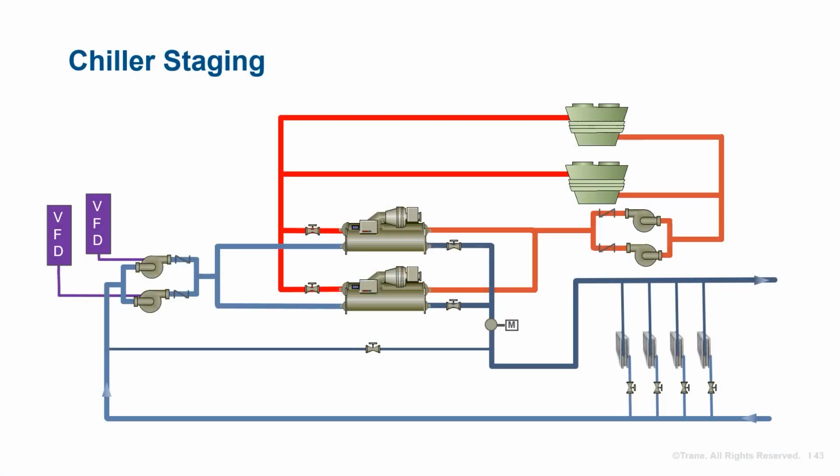The plant configuration we'll look at in more detail is piped for variable primary chilled water flow with headered pumps. The manifolded condenser pumps are constant speed. The diagram shows two chillers, but could be extended for a larger plant with more chillers, including a swing chiller. We'll touch briefly on that case in a bit. Other plant variation diagrams are included in the appendix, with associated sequences in Section 5, including pumped coils and waterside economizer, to name a few. Let's start with equipment staging.